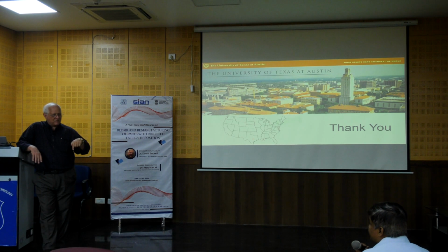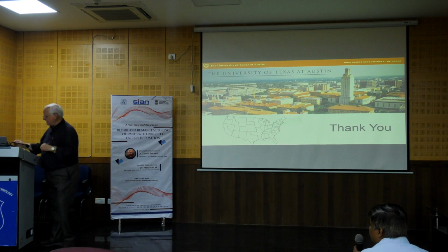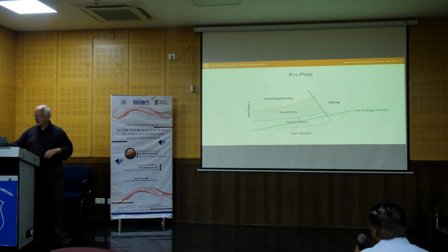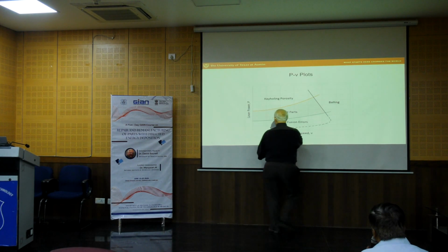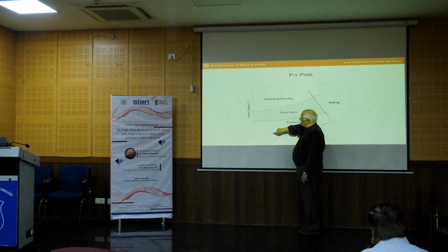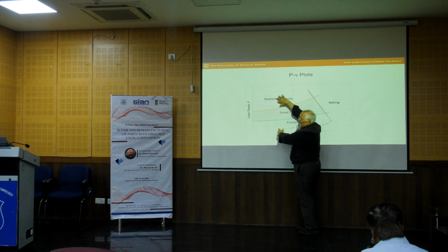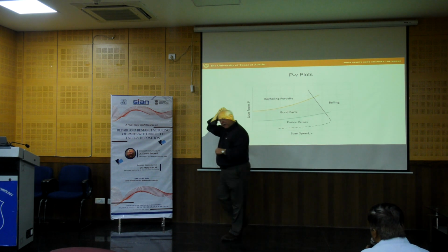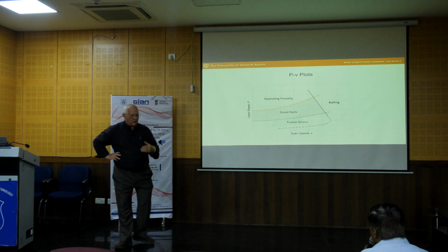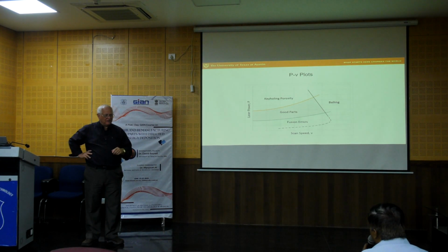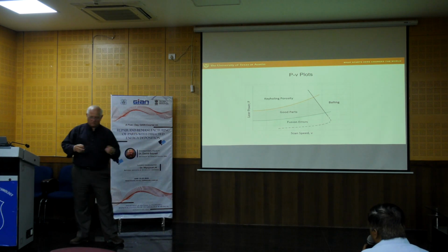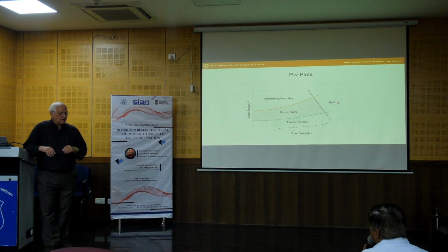We go from a low power to a high power, which effectively cuts across this plot, right along here. So it cuts across here, so we can see the entire span of the process, and we're reasonably sure that we'll hit the good spot, the good part area. We do that run, then we inspect the parts, do microscopy or tension testing, whatever we need to do on the parts.